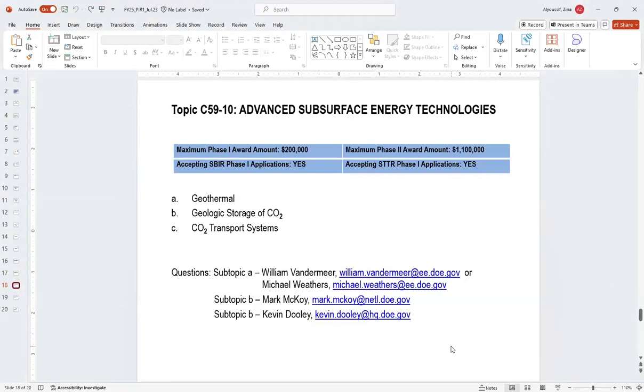For this go-round, what we wanted to focus on was mineral scaling. What that refers to is that there are various minerals in geothermal brines that can end up precipitating in the subsurface, in rock fractures, on casing, within the well bores, and also within surface equipment, such as pipes or turbines. The precipitation is usually a result of temperature or phase changes within the geofluid.